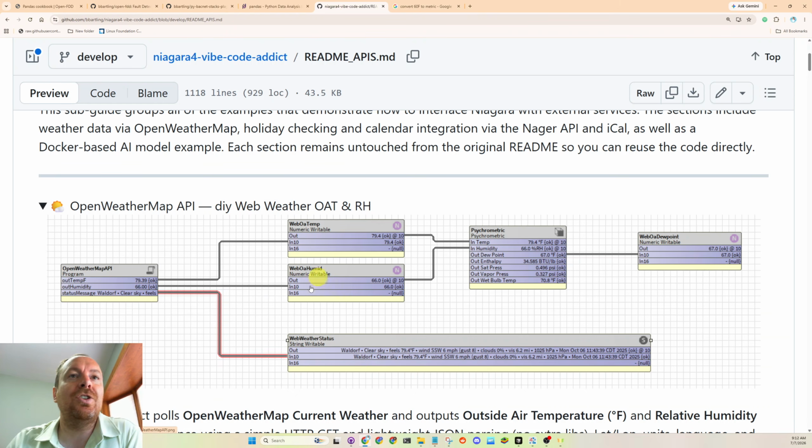Don't use the conversion in Workbench, where there'd be another block where you convert it. Just hard code your Fahrenheit or imperial units to metric rather than converting the units in Workbench, because it just gets really messy. Try and dumb it down, and then once your units are hard coded in metric, it makes sense to you.